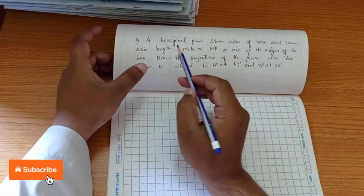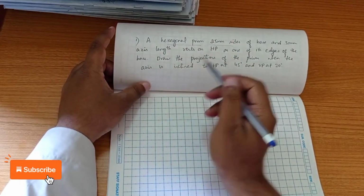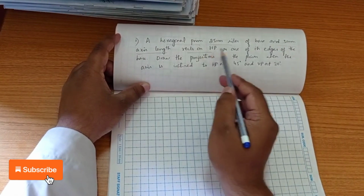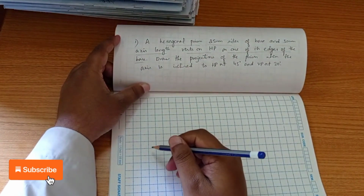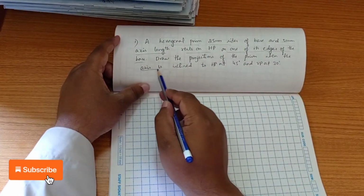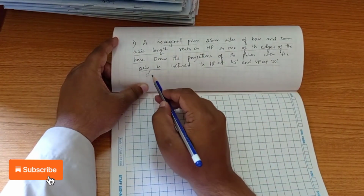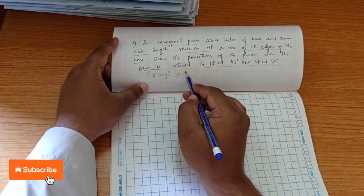Okay, we see another problem on a hexagonal prism. So you can see that we have to construct a hexagonal prism with a hexagon of dimension 25, axis length 50 mm. It rests on HP on one of the edges of its base. So we have to construct a hexagon with respect to the base edge on the right hand side. Draw the projections of the prism when the axis is inclined to HP at 45 and VP at 30. So when the axis inclination is given, it is a beta angle problem.